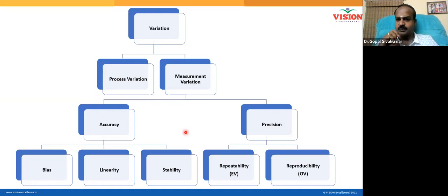Right? If you ask me to measure an item multiple times, let me say you want me to measure 100 mm 10 times. You have given me the standard piece of 100 mm. And all 10 times, when I give you the same reading, then my readings are repeatable. I measured the same item repeatedly multiple times, and repeatedly I am giving you the same reading. Then I am repeatable. Similarly, suppose same item, after I measure, now you are measuring. If my readings and your readings are not matching, that means we disagree with each other. But both of us measured the same item. I also measured 100, you also measured 100. Ultimately, we both should come out with the same number. But if that is not happening, that disagreement is called reproducibility error. If we agree perfectly, then we are perfectly reproducible, right?